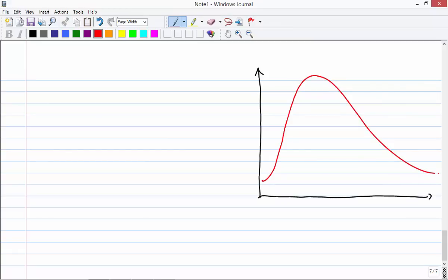When you are solving for Brayton, Otto, Diesel, jet propulsion, there is no saturation line because there's no phase change. It's air, and air remains air. It doesn't condense, at least in the temperature limits that we are working at. But here in the Rankine cycle, yes, because we condense it.